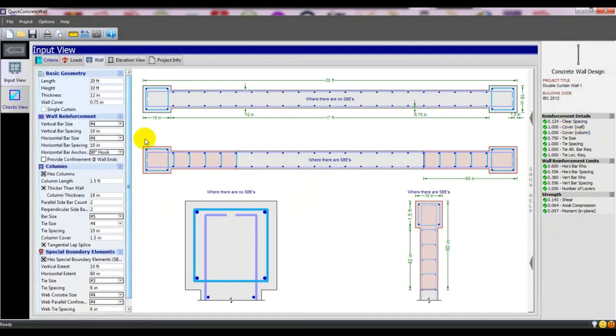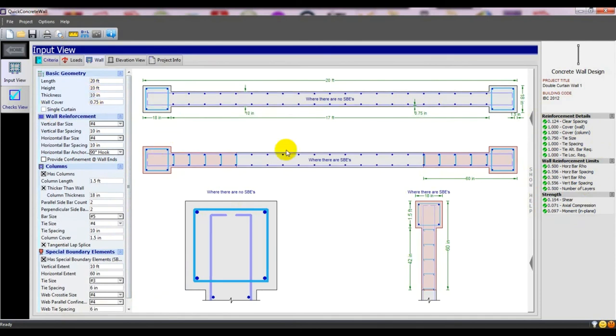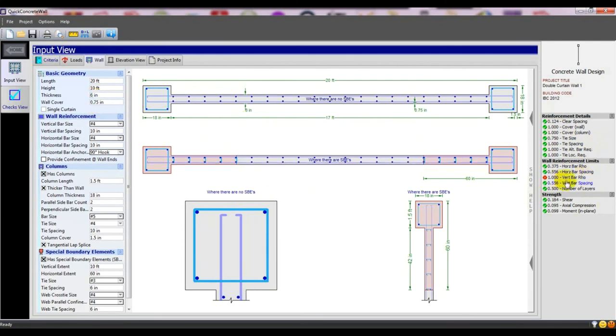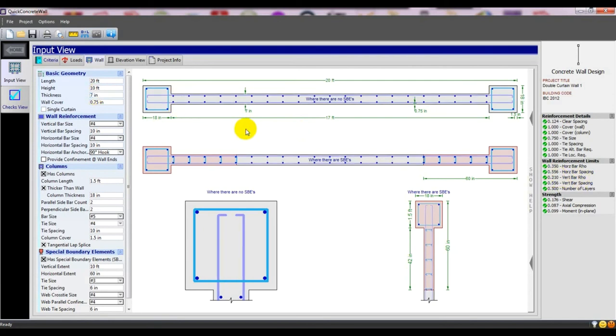Now suppose we see that the thickness of the wall is okay for our design load. So we'll go here and reduce our thickness. If we use thickness 10 inch, it's also okay. Our design is also okay if we use 8 inch, it's also okay for our load. Now if we go for 6 inch, just see here, for 6 inch it's not okay. So if we use 7 inch, for 7 inch it's okay.